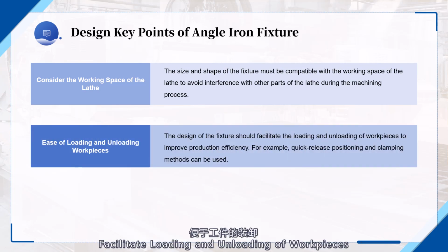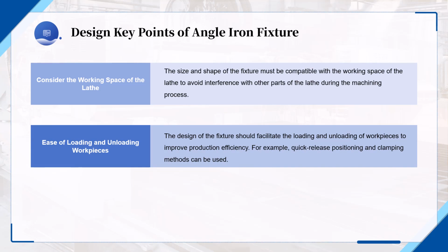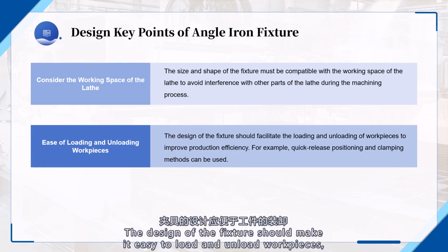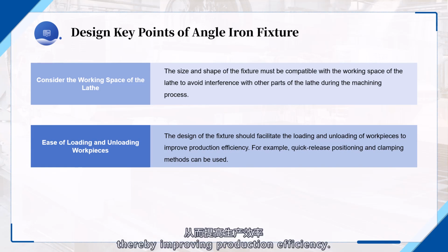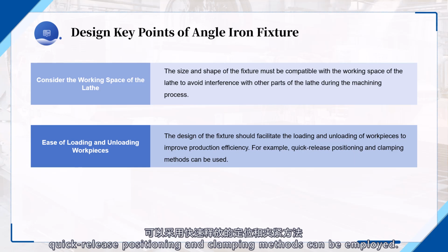Facilitate loading and unloading of workpieces. The design of the fixture should make it easy to load and unload workpieces, thereby improving production efficiency. For example, quick release, positioning, and clamping methods can be employed.